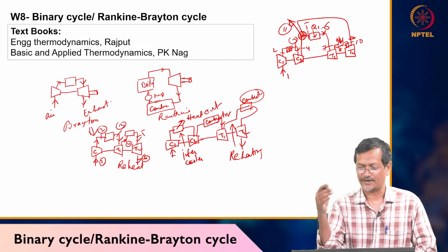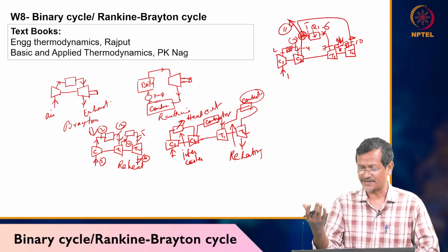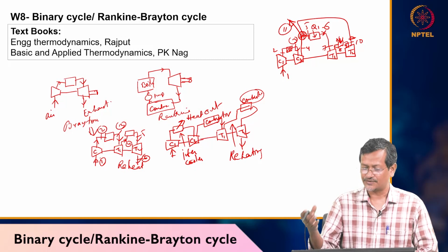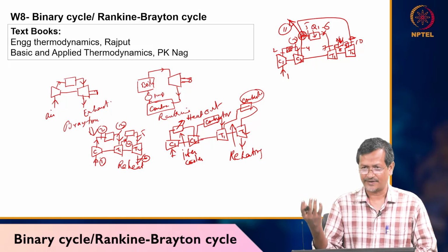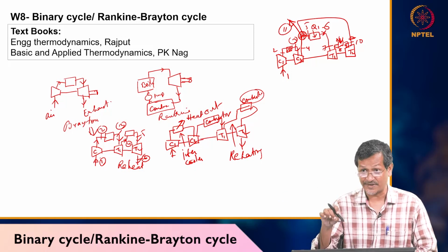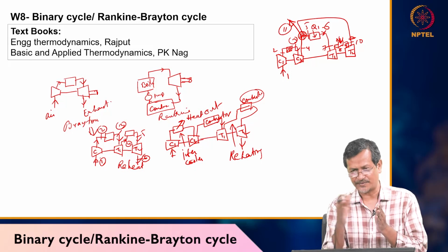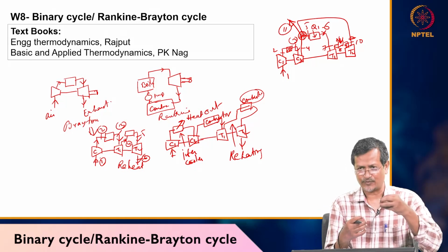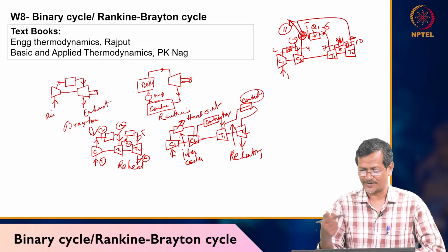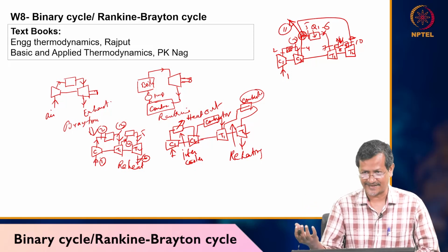actually heat exchanging happening. What is happening, T2 rejecting lots of heat, exhaust gas is going out from T2, so that high temperature fluid, high temperature exhaust gas will be used to increase temperature of compressed air, because compressed air from C2 to combustion chamber is going. If you can increase certain amount of temperature, it will be beneficial for us, so we can recover some amount of heat from exhaust gas.